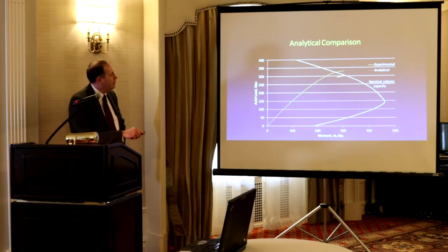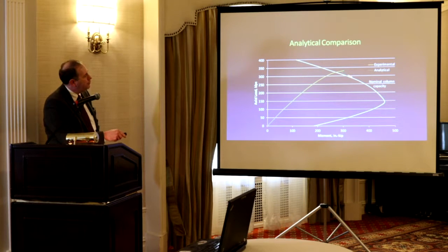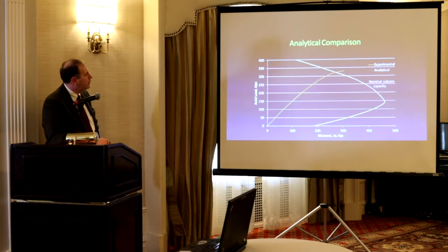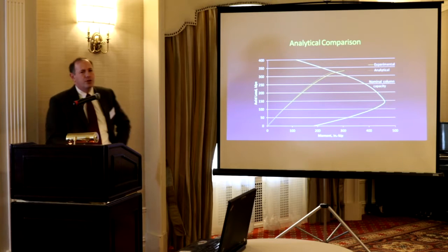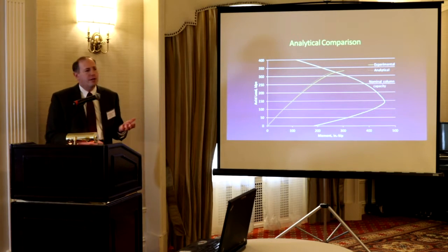And this is the experimental curve. So it comes up load, you see the second order. If there were no second order effects, it would just be a straight line up, but second order effects come over. And nice, the capacity was predicted conservatively by the code. So that's good, this is where it fails, outside of that curve. This is what our analysis can do. Just using those regular assumptions, we can follow that curve and predict it very well.